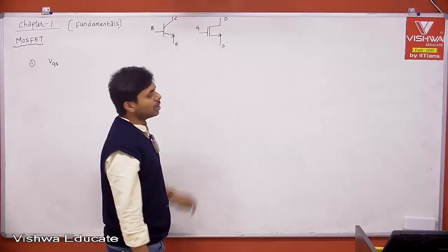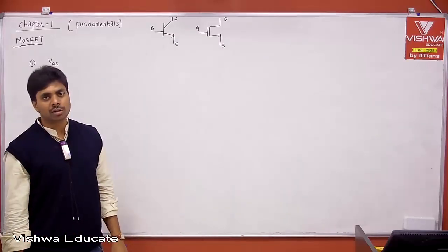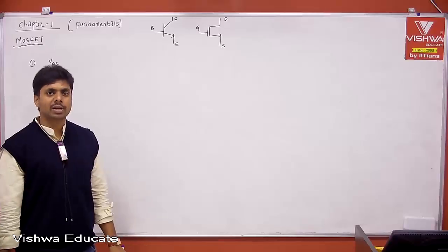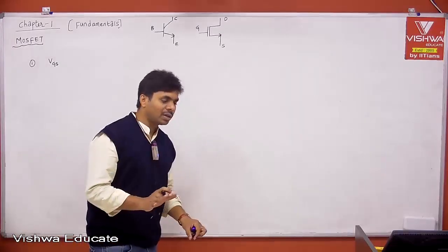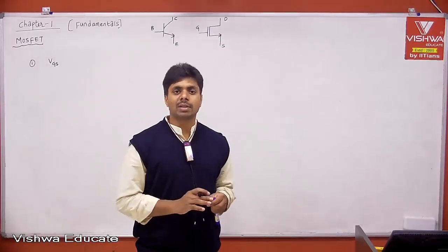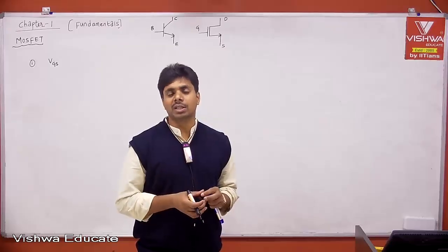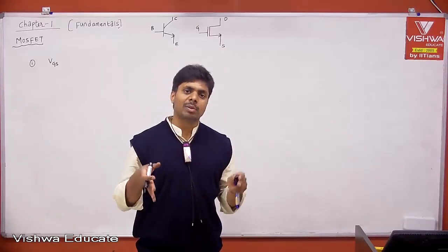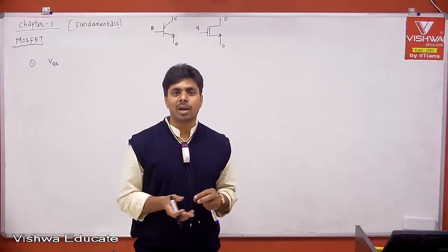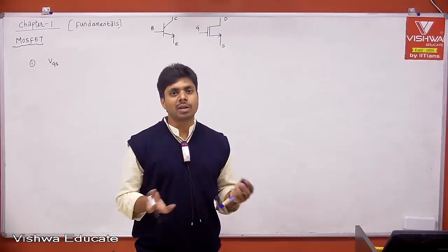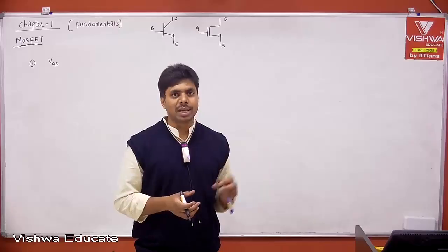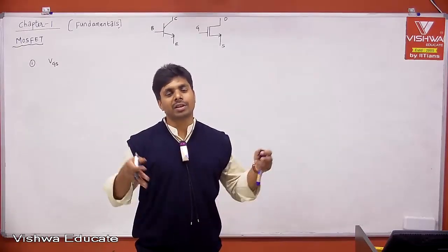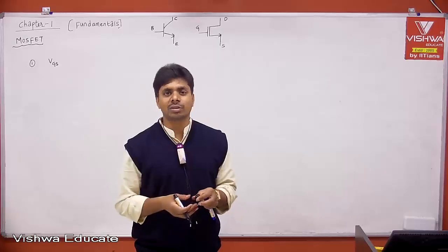Similarly, there is something called threshold voltage, because I am explaining for enhancement type MOSFET. That is the typical transistor. When I speak about MOSFET, that is typically enhancement type MOSFET, not depletion type MOSFET. We have depletion type MOSFET also. What does it mean? The channel will be present from the fabrication point of view from time t equal to 0 without applying any gate to source voltage. But this is enhancement type, which needs the channel to be formed before applying drain to source voltage to get the current through the channel.